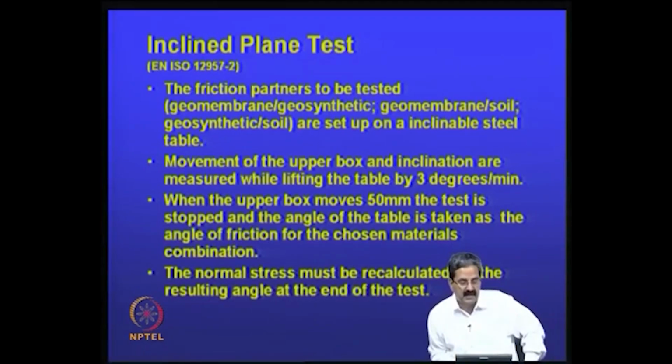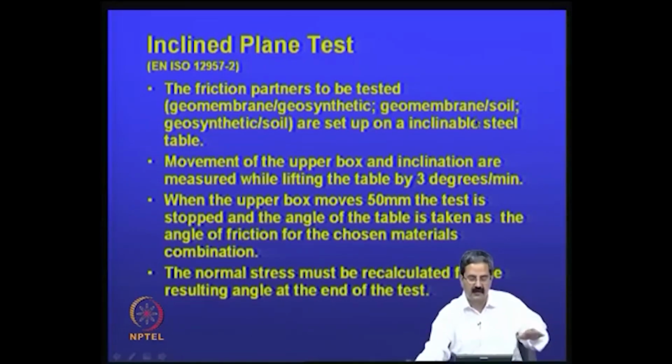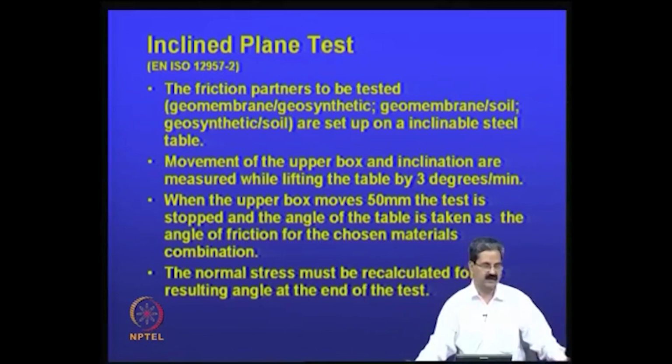There is also another test called the inclined plane test. Here we measure friction parameters between materials, like geomembrane to geosynthetic material. There are so many frictions between two materials: geomembrane to geosynthetic in a landfill, geomembrane to soil, geosynthetic to soil. Whatever the combination, you place it on an inclined surface; for example, one can have a table like this, any table.